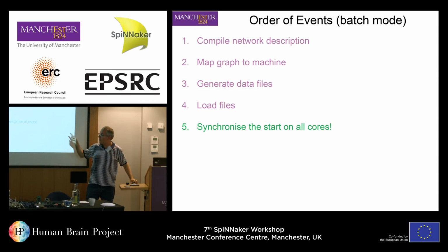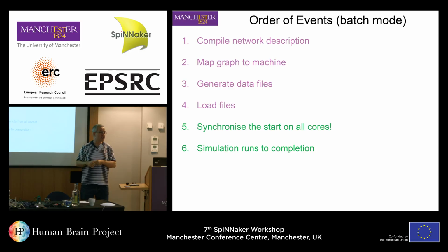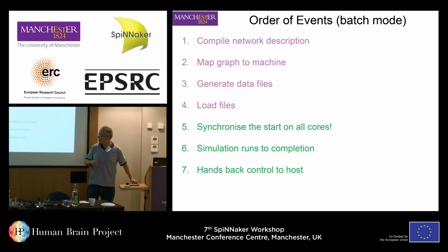So the synchronization calls everything to start at the same time, and then if you said run for, I don't know, 10,000 milliseconds, it waits that length of time, and then hopefully all the cores say, yes, I've completed. There is a polling going on from the host to say, have you finished yet? And when everybody says they've finished, controllers hand it back to the host, which then pulls back all of your data.